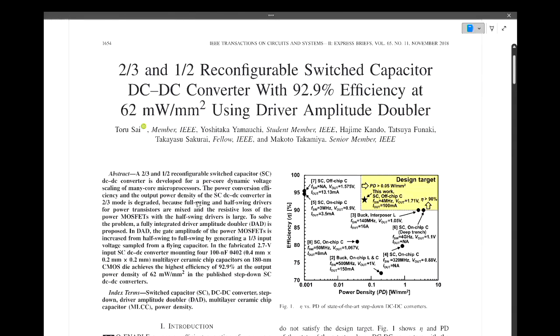During phi 2 you connect both of these to ground. During phi 1 you connect both of these. So you've got virtual ground here, and you connect this one to virtual ground. So you've got 0 volts here, and whatever voltage you change here is going to charge this capacitor up directly. So it's charged during phi 1, right? Yes. Then you disconnect this from the circuit during phi 2.